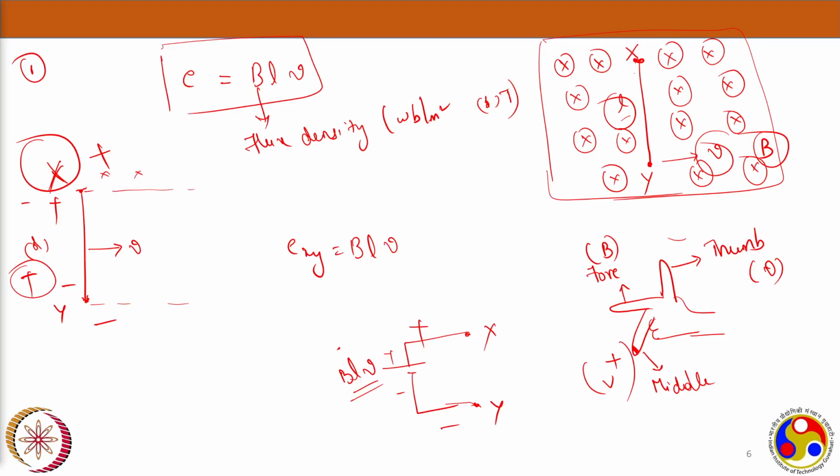Now, before going into Fleming's left hand rule, if you see the magnetic field polarity here, let's say I'm reversing the polarity. Now I have placed the north pole on the bottom of the paper and the south pole on top of the paper. It will just be dots here instead of crosses, right? All the dots will be there, and dot means coming out, coming towards you. Now I'll quickly apply Fleming's right hand rule. My thumb denotes velocity.